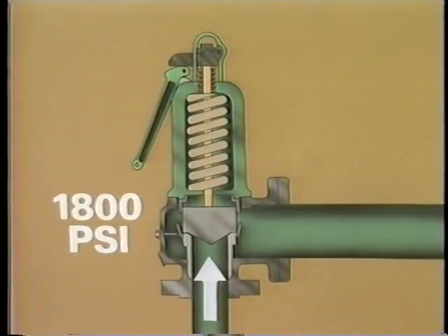Now that you have a basic understanding of how safety valves work, let's look at how they are used to protect the boiler from overpressure. As you learned earlier, the superheaters and reheaters in a boiler are designed to carry superheated steam at designated pressures and temperatures. The flow of steam through superheater and reheater tubes is important for a number of reasons. Steam flow is necessary to drive the turbine generator, to cause an efficient transfer of heat from the flue gas to the steam, and to keep the superheater and reheater tubes cool by removing heat from the tubes.